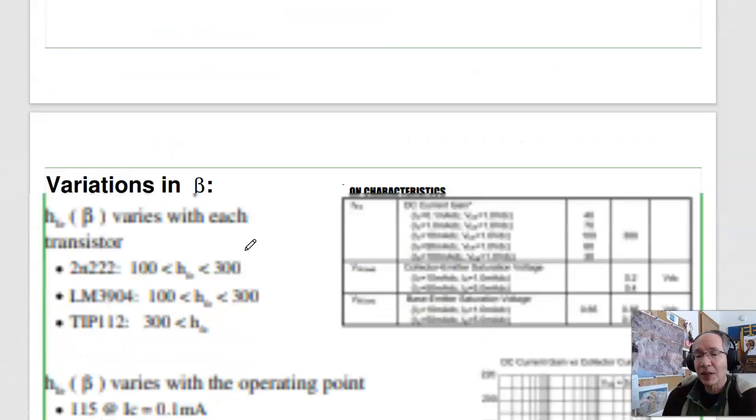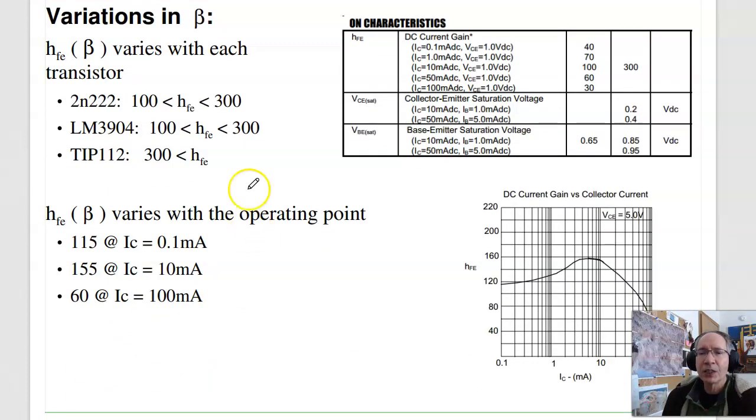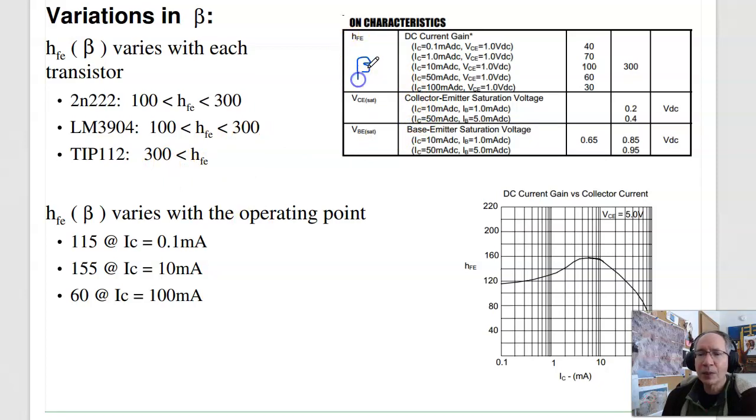That's actually valid. If you look at the data sheets for a 3904 transistor, the current gain, HFE, some textbooks call it beta, some call it HFE, depends on your textbook. This says that the minimum gain is somewhere between 40 to 30. Under this operating point, the minimum gain is 100, maximum gain is 300. So the gain is somewhere between 100 and 300. There's a lot of variation in beta. So what we assumed, 200, the middle number, is perfectly valid. But Circuit Lab assumes 154 is perfectly valid.